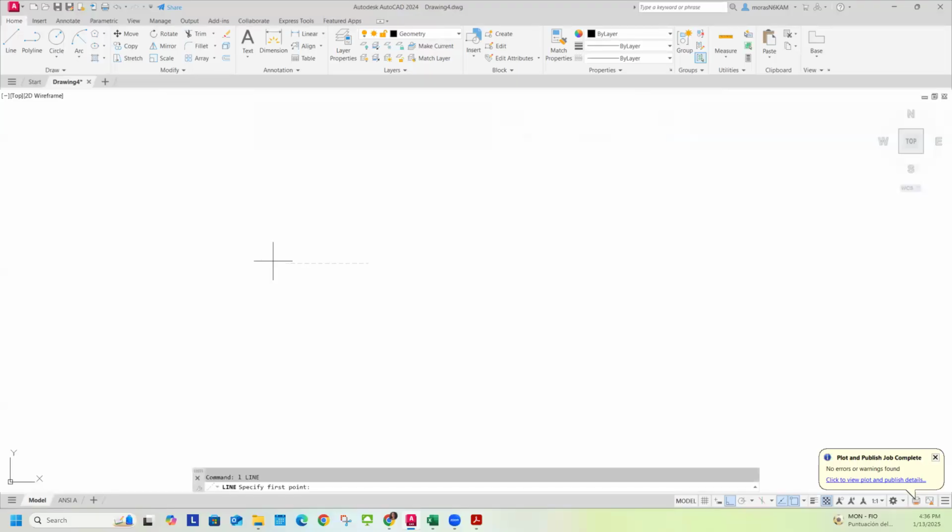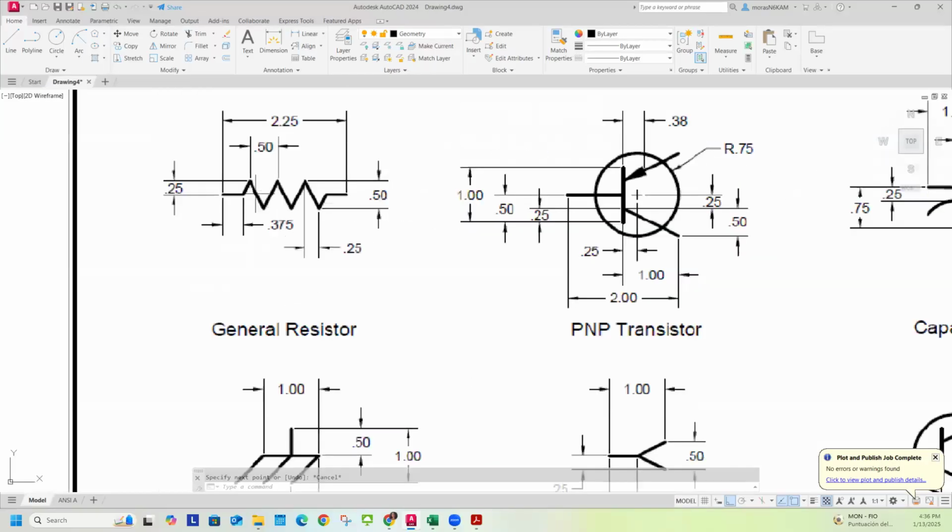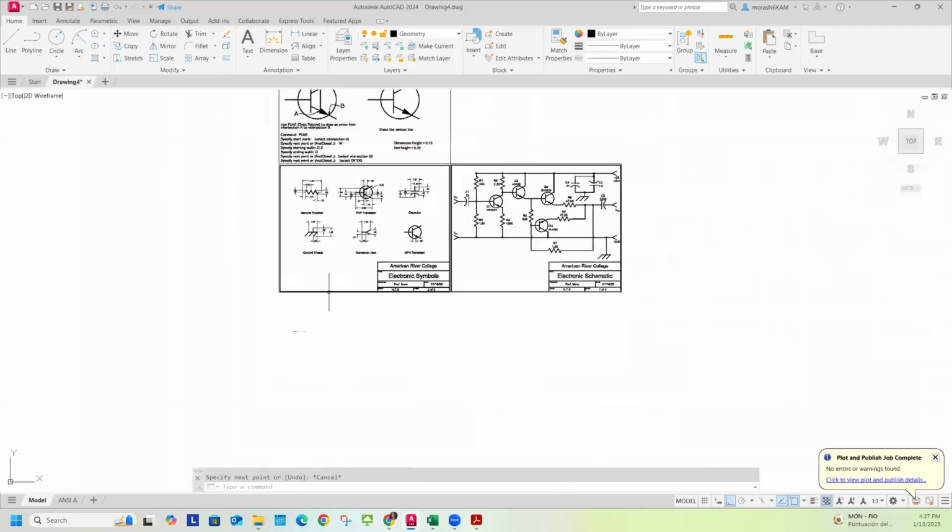All right, and actually I'm going to change this to the construction layer because that's my overall length. And then that first part of the line is 0.375 units. And then it goes up. It's made up of these peaks and troughs. So it has this triangle and they're 0.5 in width and 0.5 in height. So I'll go ahead and make that shape.